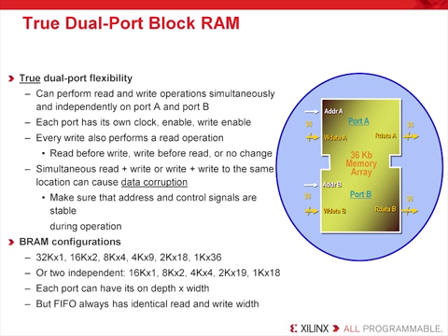As I mentioned, these block memories are true dual-port RAMs. This means you have a ton of flexibility, and likewise, you need to make sure you're using them properly to avoid problems. You should remember that read and write operations are done simultaneously and independently on both ports A and B. This means that each port has its own clock, enable, and write enable ports.